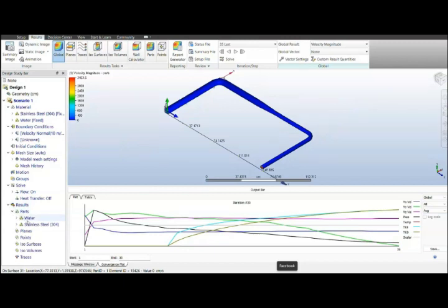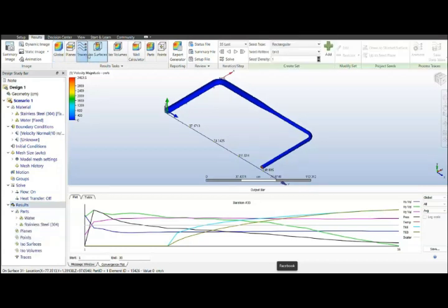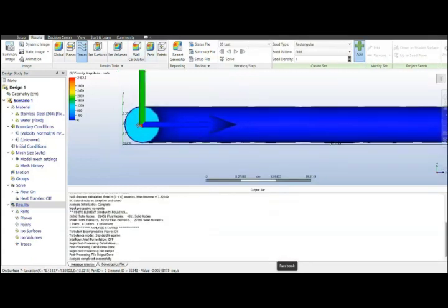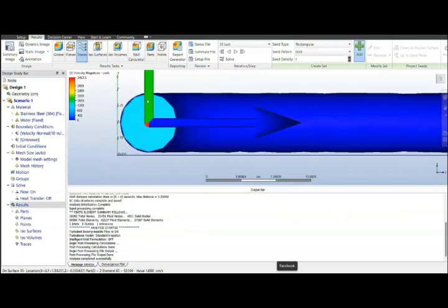As you can see, I click water, click stainless steel, and this is our material. This is our mechanism, the flow, which is water. So we click traces and we click add. Then we have to make a dot at the hole of our pipe.